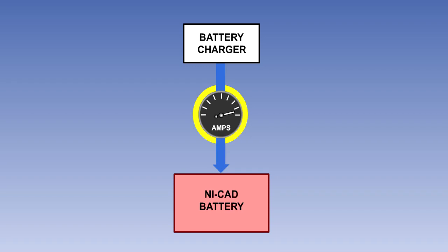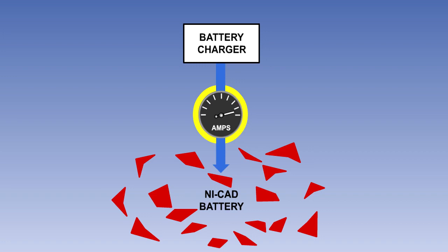This condition is known as a thermal runaway and can cause so much heat that the battery may explode. For this reason, the charging of a NiCad battery must be closely monitored.